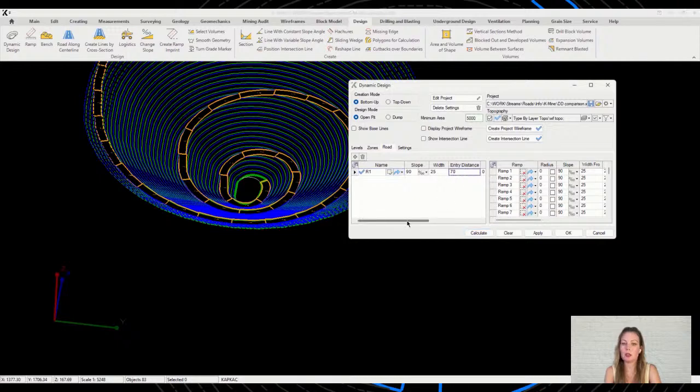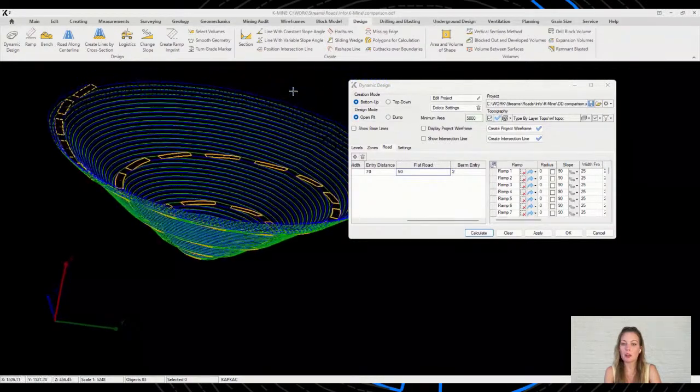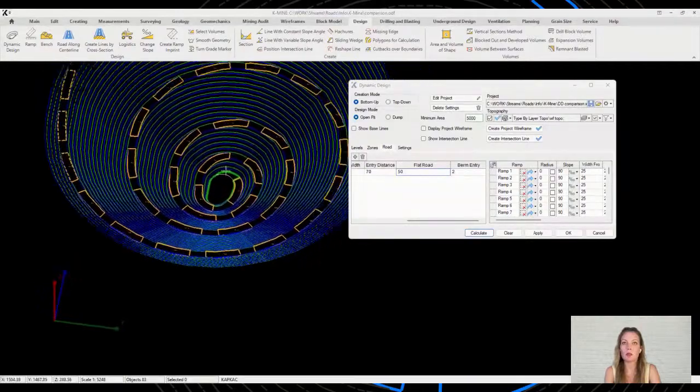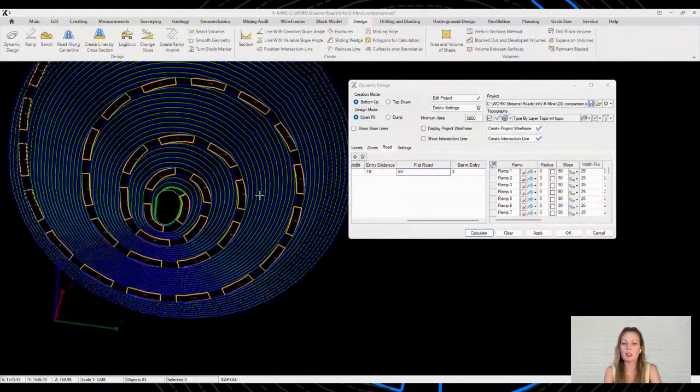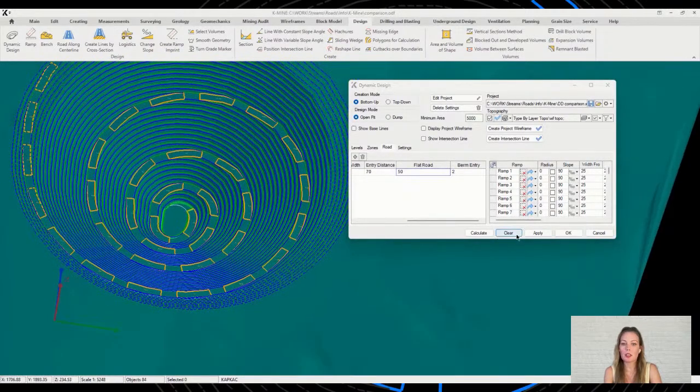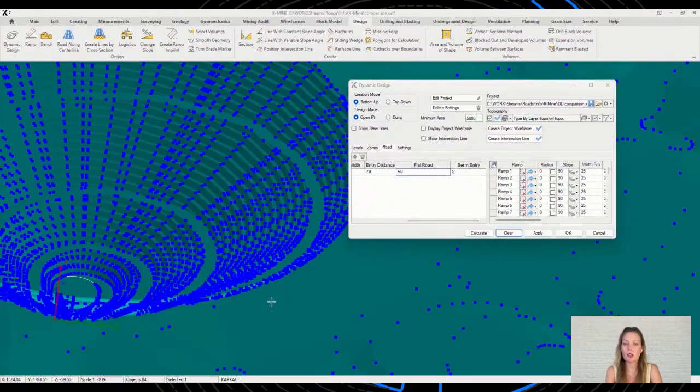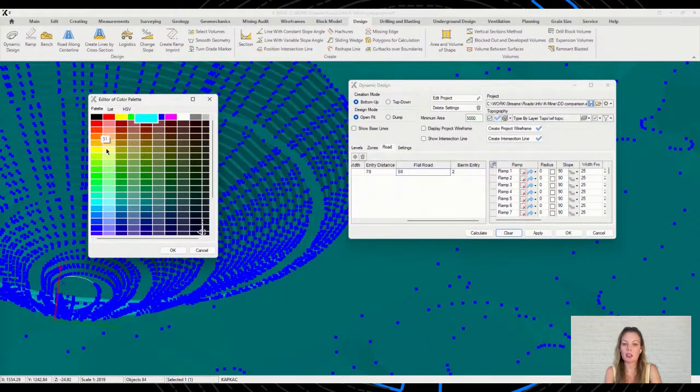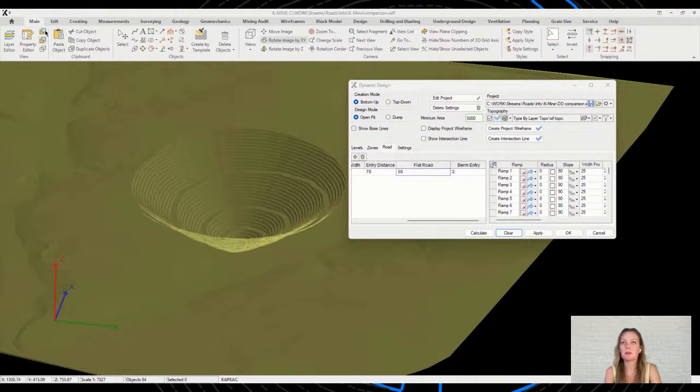The next step is to build a similar quarry, but with the participation of horizontal inserts. For clarity, we assume that at each level there will be a horizontal insert 50 meters long. We will see how this will affect the project further. In the same way, we build a design frame taking into account the topography, give it different colors, and save it under a different name for further manipulations.